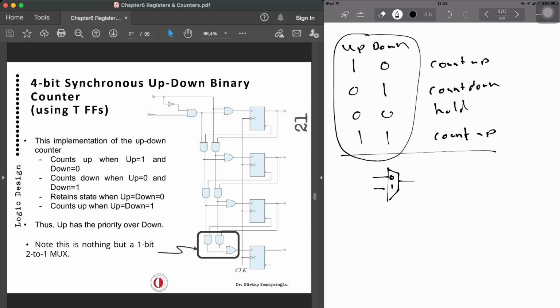First, we have to derive the state diagram, then the state table. From the state table, we have to find out flip-flop input equations in order to derive these combinational circuits, put them onto a K-map, find the optimized expressions, then draw the circuitry. So this is the circuitry that we are going to obtain in the end. And that's for up-down counter.